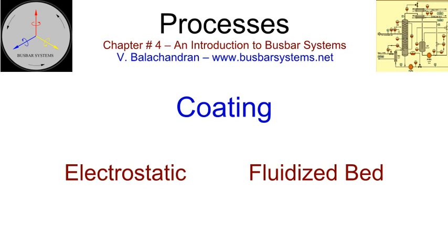In a low voltage bus duct, the clearances will exceed the minimum requirement with bare conductors, and therefore the coating, if carried out, need not be subjected to voltage test. The spacing between the conductors will be dictated more by the thermal consideration and short circuit withstand capabilities. The coating will only provide additional safety.